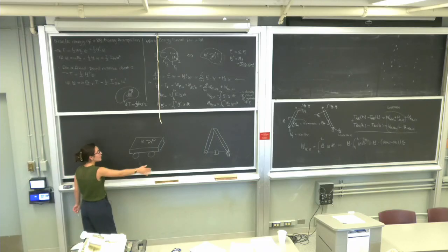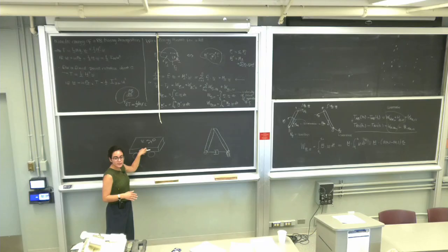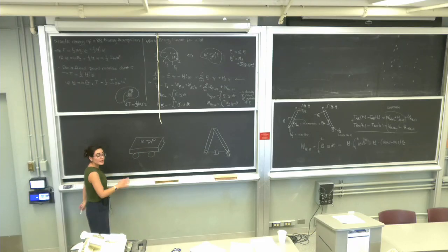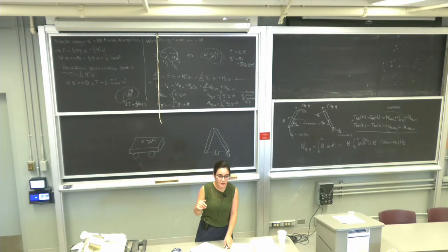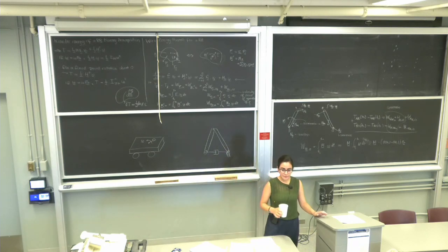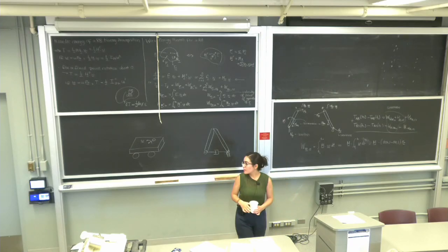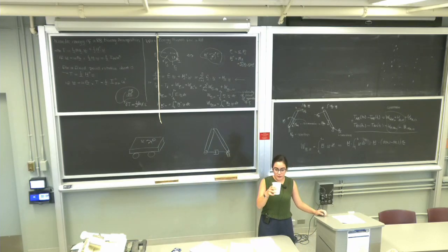Yes, because the sum of the external forces is 0. Is the angular momentum of the cart conserved during its motion? Yes, because if this is giving a moment, that's going to be a reaction moment. Is the energy of the cart conserved during its motion? No, because the motor is providing energy, right? So we have to take into account the work of the motor, the work of the motor that is providing a couple that is turning this pendulum.